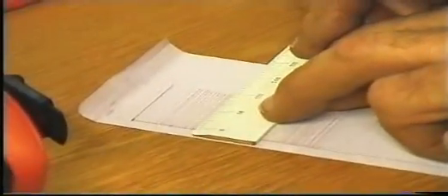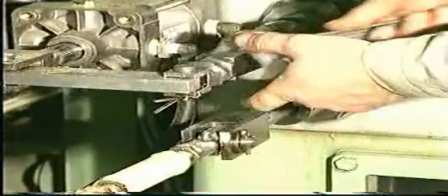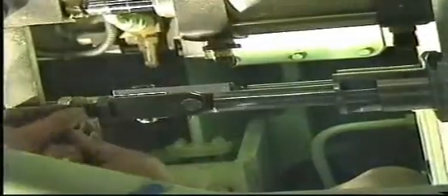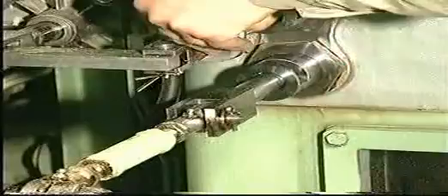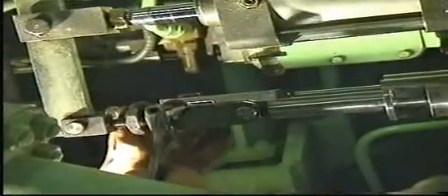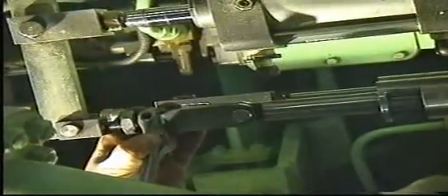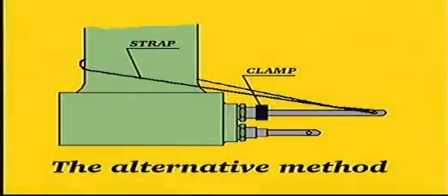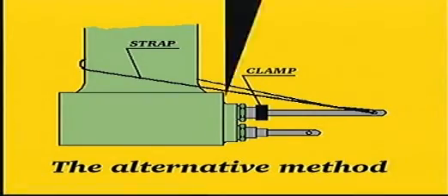Again, measure the maximum combustion pressures for each cylinder. Adjust the links or displace and lock the VIT racks so that the maximum combustion pressures, corrected to ISO ambient conditions, are uniform and have the required values. Note down the fuel pump and VIT indexes.